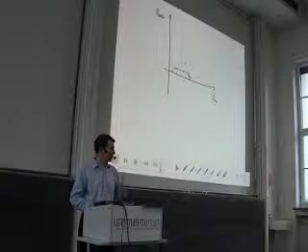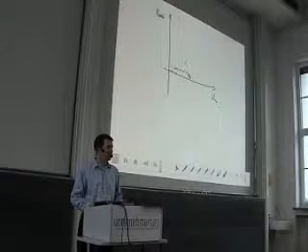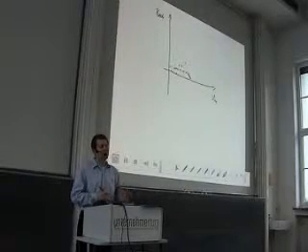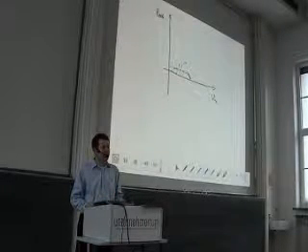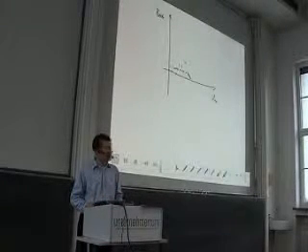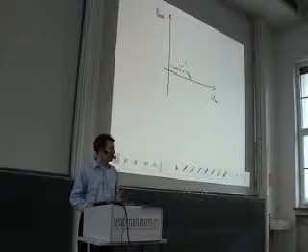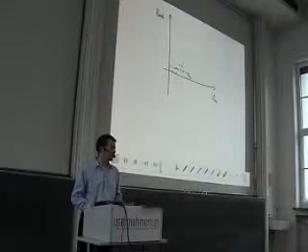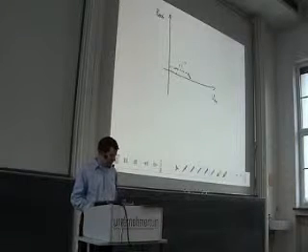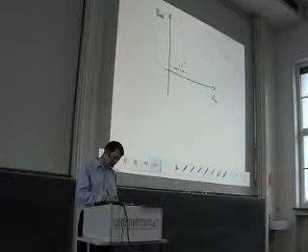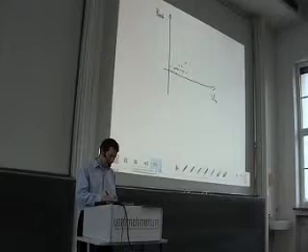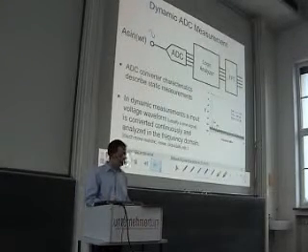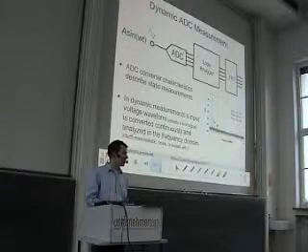This is the whole field of the sigma delta converters. These are converters that work somehow differently, and hence we cannot easily plot a step function for them. So also for this type of converters we need another measure. And for both of these cases we can use this so-called dynamic ADC measurement.